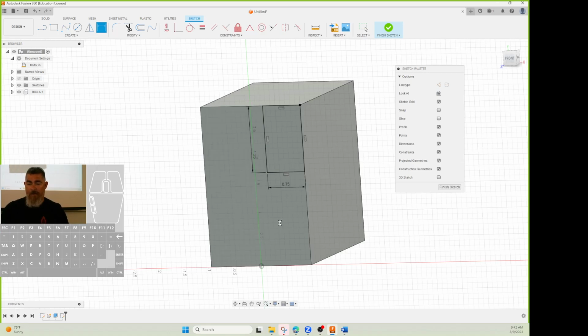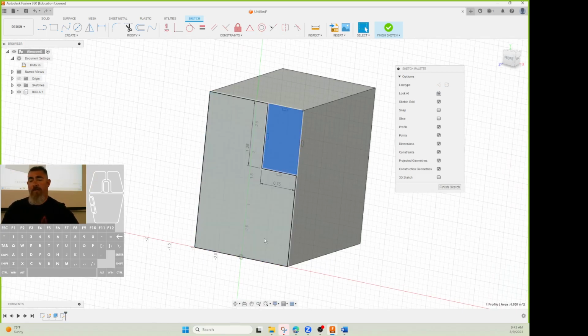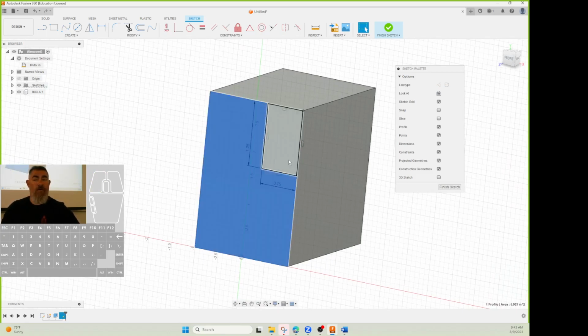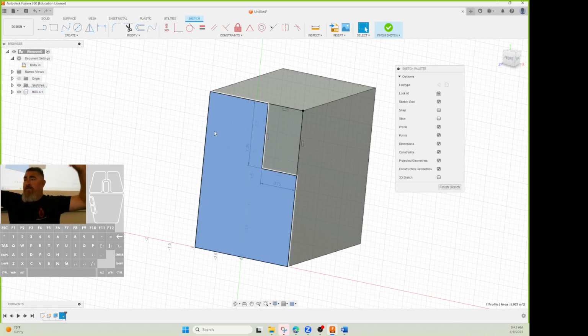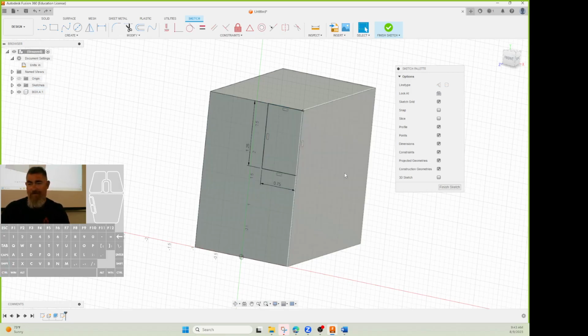and you can see that when I'm here, I have two profiles. I have a closed profile there and a closed profile there. Because it automatically takes the edges of that face and makes it so you can use them. It makes them lines on your sketch. I could just double click here and delete that. But see, oh, I lost that corner now. So don't do that. Just leave them there. Because now I can pick what I want.